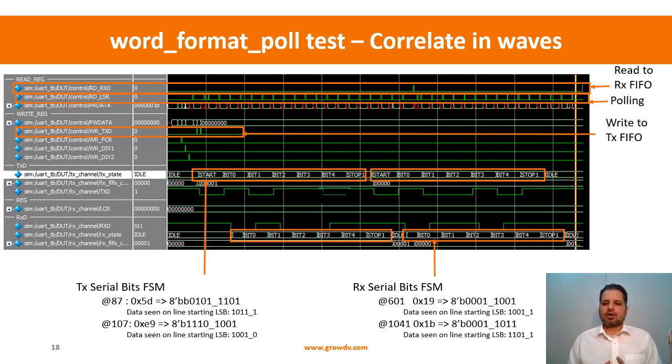However, this test has not failed, but the principles that I am showing you are what you need to follow even in your real-life debug cases, right? So the first step, you should not directly jump into the waveforms. That's the general practice all of us have when we start off doing verification, because we would have done some small example simulations, and in those cases we have generally looked at the waveforms. So there is a tendency to jump into the waveforms as the first step. You should not do that.